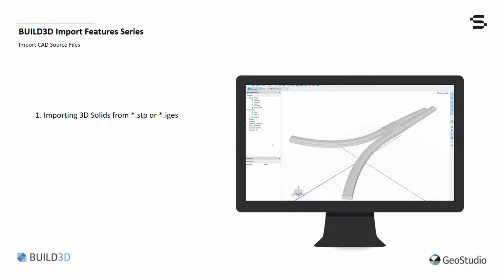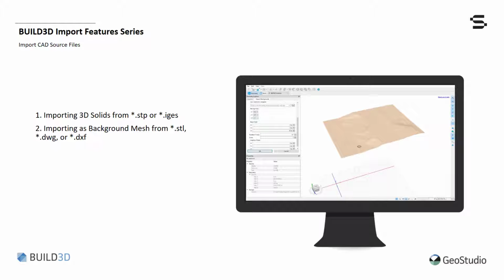There are three methods for importing CAD-generated geometry into Build 3D. The first method is importing as 3D solids. Three-dimensional bodies can be imported directly into Build 3D if they are in the STP or IGES file format. The second method is importing as background mesh.